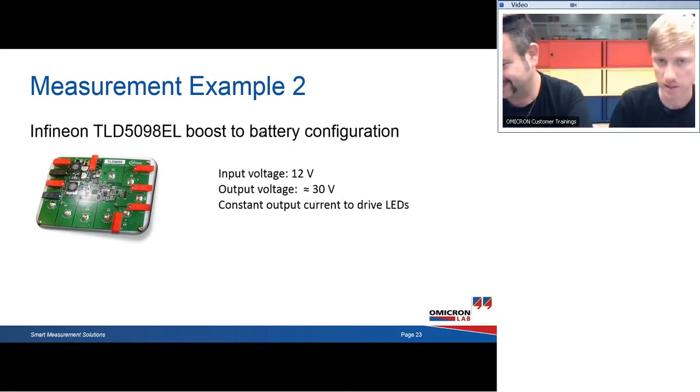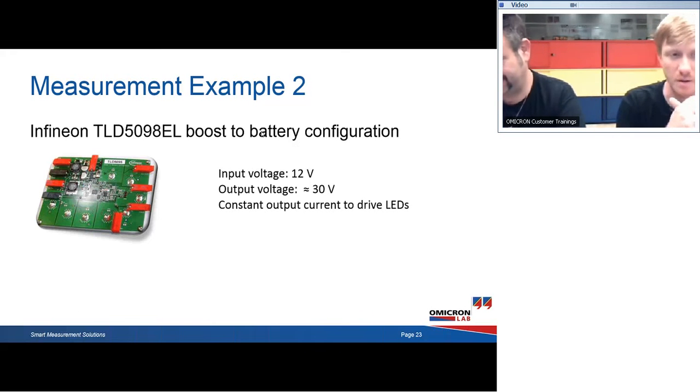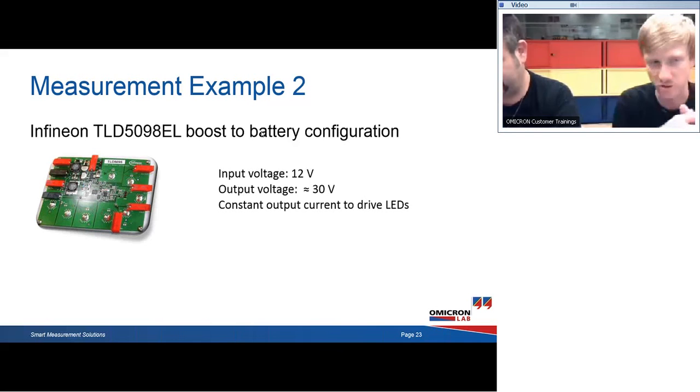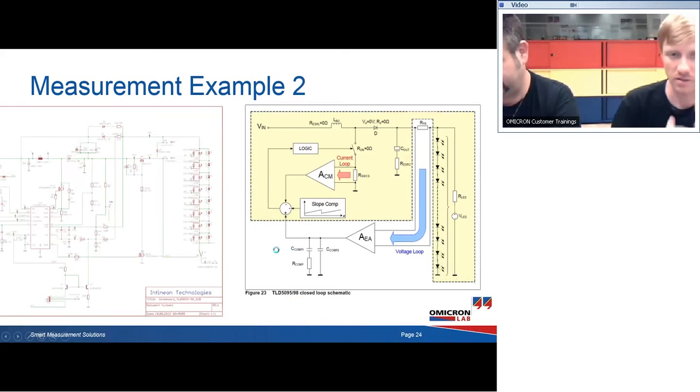And it's a boost LED driver that boosts a 12-volt battery voltage to a constant current through the LEDs. And since there are many power LEDs connected in series, we need up to 30 volts to drive the current through the LEDs. And the circuit looks like that. We have all the LEDs here on the right hand side of the left picture.